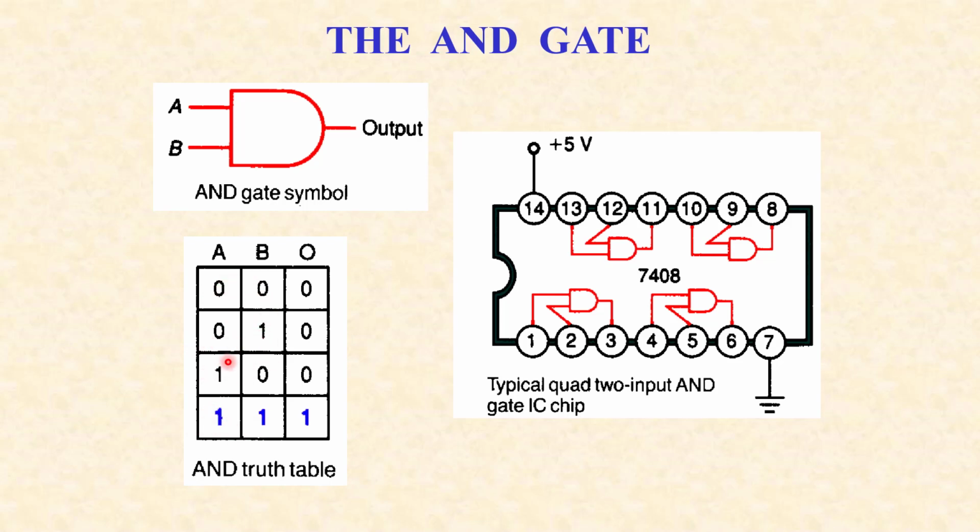So these are the different possibilities that these inputs could provide. But the way that this logic works is the output provides an output only based on the states of these and what's inside here. So for an AND truth table, the only time we get a 1 is if all inputs, regardless of how many inputs we have, they all have to be 1.